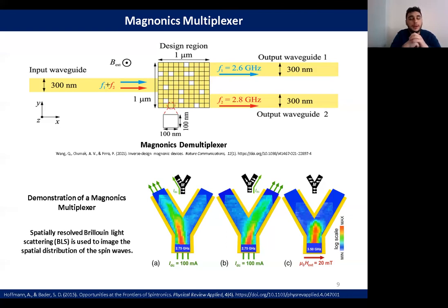As you can see in part A, destructive interference is observed in the right path, while constructive interference is observed in the left path. In short, local magnetic fields enable the spin waves to be selectively steered to the left or right side. On the other hand, the transverse magnetization state causes a strong non-uniform internal field distribution. In figure C, since the load currents are replaced by a uniform external magnetic field, the spin waves end at, we can see, the connection point.